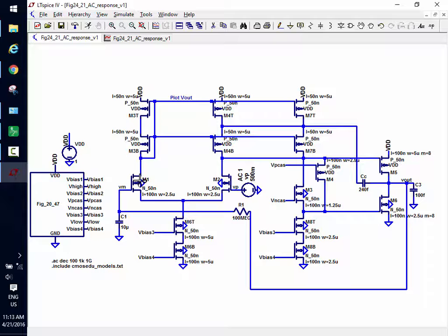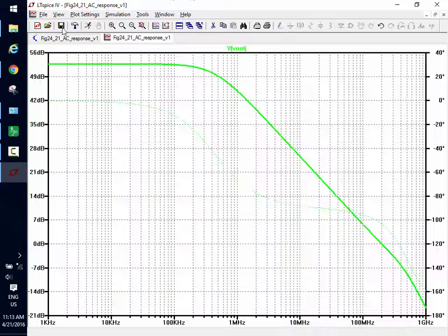It's just the input common mode range of the diff amp. That's limiting my output swing. Does that follow, everybody? So when you design your circuits, if you use this topology, you're probably going to be limited by the diff amp as your output swing, because the diff amp has to stay on as the output is swinging. So let's hit save.